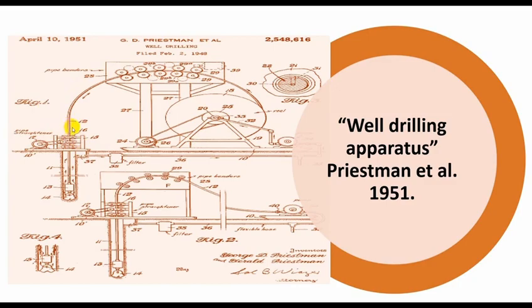Okay, this is very close to the drum currently used in coil tubing, the gooseneck currently used in coil tubing, and the injector currently used in coil tubing, but no pressure control equipment. And there were rollers in contact with the pipe, not chains like the injector nowadays. So here there were rollers in direct contact with the pipe, not chains. Here were rollers like the gooseneck. The gooseneck currently is rollers.